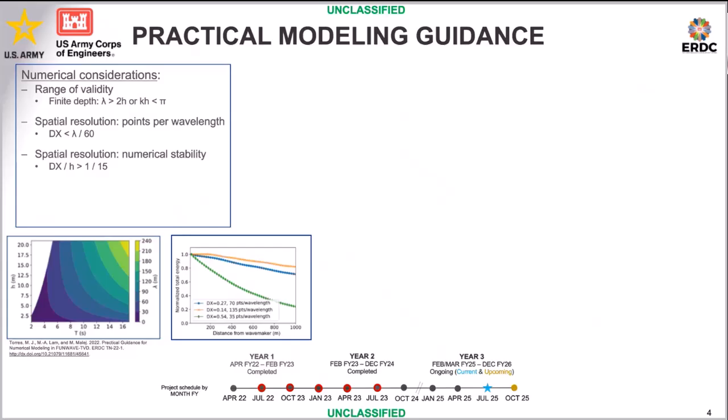and a little bit beforehand, it gives you a quick lookup as to, can I run FunWave here? What is it going to be good at resolving in terms of peak wave periods, for example? And what do you need to consider for spatial resolution requirements, both on the physical level, so resolving the physical processes well enough? You need enough points. However, the numerical method can only handle so many points. And then there's the numerical stability. So that's the kind of info.